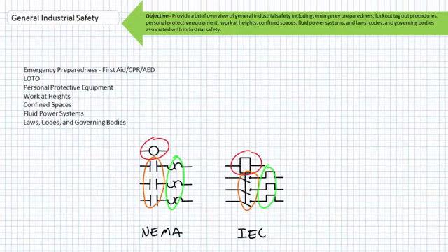Finally, the philosophical differences between the NEMA and the IEC can be summated as a difference between robustness and specificity. Components like contactors designed by NEMA specifications have a tendency to have a broader application range, whereas those designed to IEC specifications are more selective and purpose-built. Depending upon your application, this could be viewed as an advantage or a disadvantage.